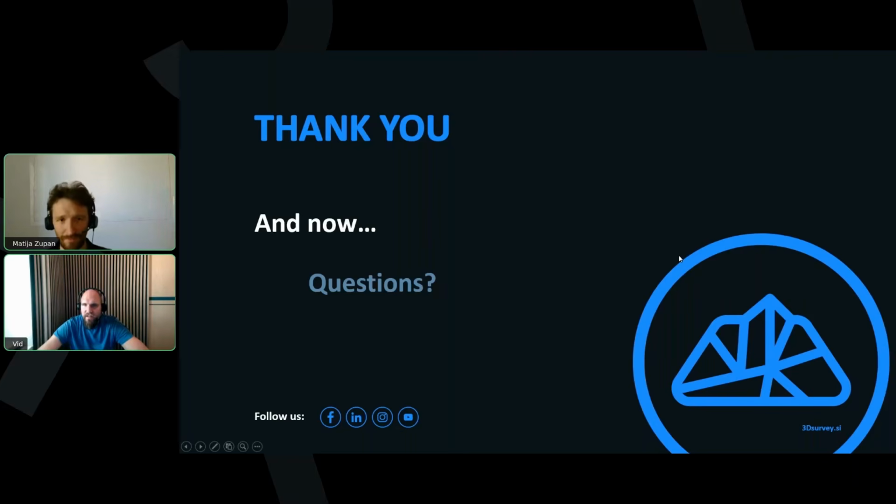Okay, the next one: would you please introduce the programs you used for managing point clouds and drawing? We basically already touched on this subject. We used 3D Survey, and in this case we used software called GoPost, which came with the StoneX SLAM scanner, just to get to the point cloud. The next question is also related: how do you upload panoramas to a project? If your SLAM scanner has the ability to record panoramas, you will typically have an option to export those panoramas along with the point cloud. Those panoramas are then automatically stored in the E57 file format.